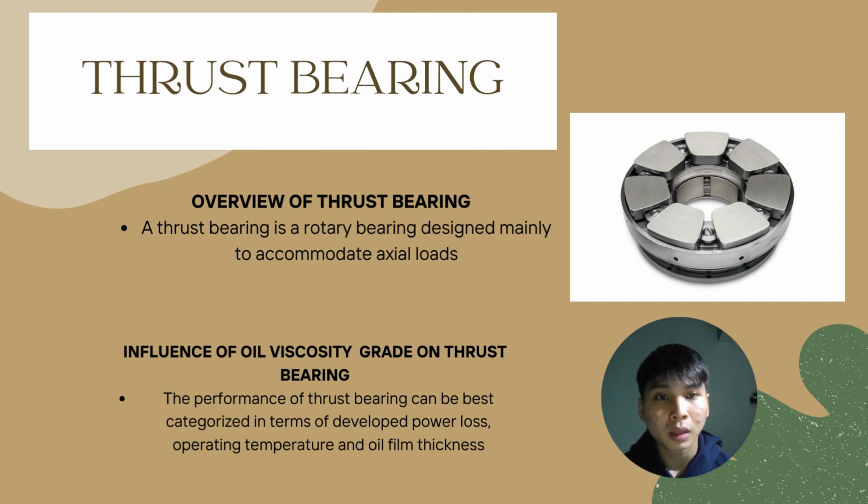Normally, thinner oil provides lower energy consumption and lower operating temperature. There are three types of oil used in this project, which are SAE50, SAE20W40, and SAE15W40. The properties of this oil will be discussed by my friend in the discussion part.